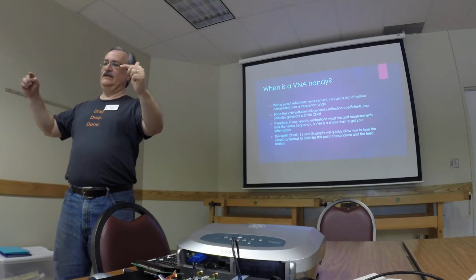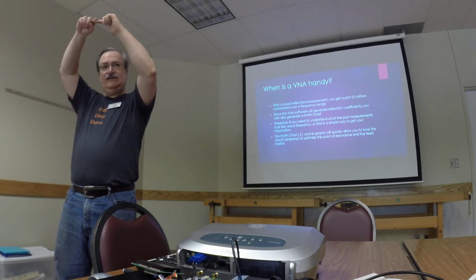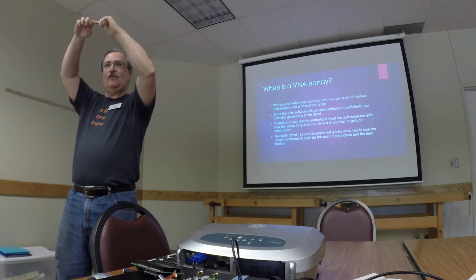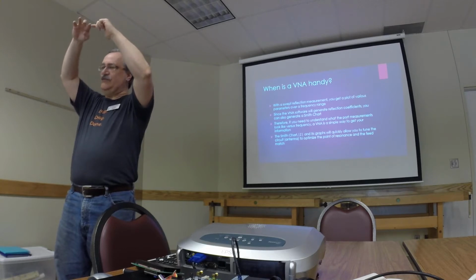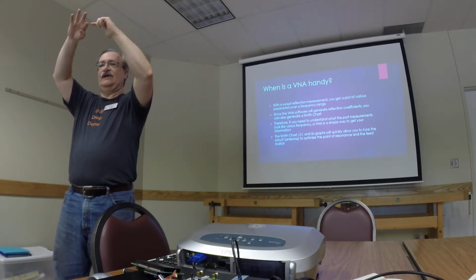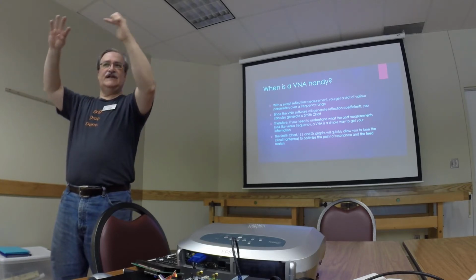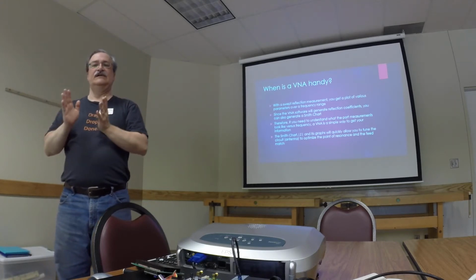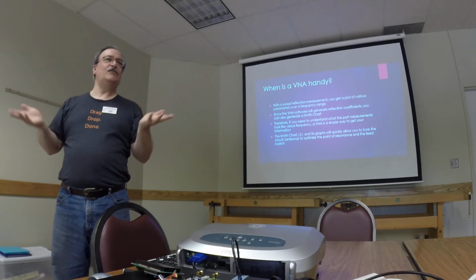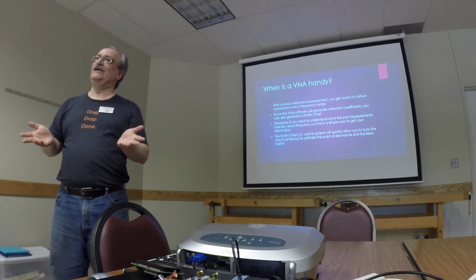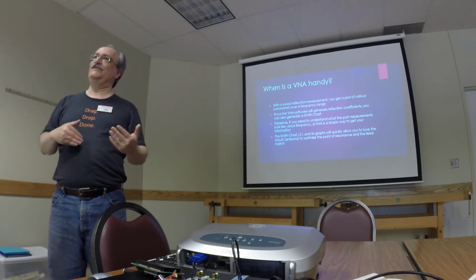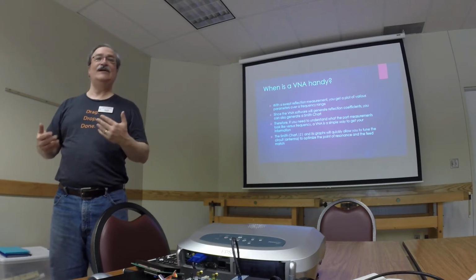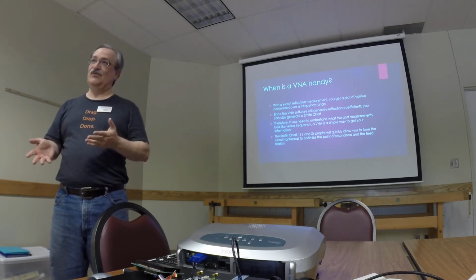On an off-center fed antenna, this is just general information in case some of you don't know this, the current maximum in the middle is still at the middle of the wire, just as if you were feeding it center fed. So nothing really changes that way, except the feed impedance changes. So, dumb me, I figured, well, I'll put a 4-to-1 balun in there to go from 200 to 50 ohms, until I found out through John Kraus's book.